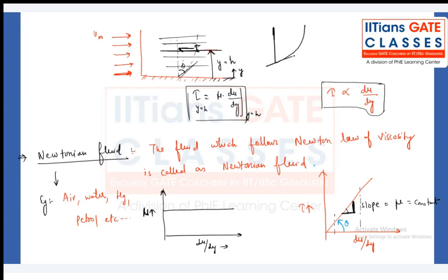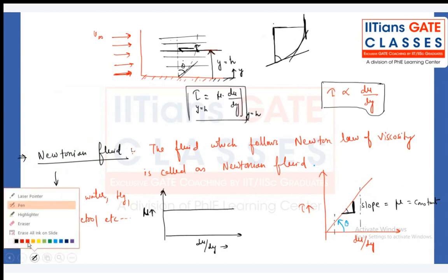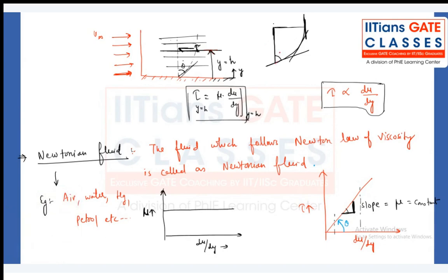Suppose you have the velocity profile something like this. Don't you believe that the gradient is changing continuously? Tell me guys, what do you believe? Whether the velocity gradient is continuously changing in the y direction. Here it is maximum, theta 1. Here what is the value? Theta 2. Here, what is the value at 99% of the free stream velocity? Theta 3, which is 0. So it is continuously changing. So definitely, whenever we are finding tau, we need to keep the value of y at that location.